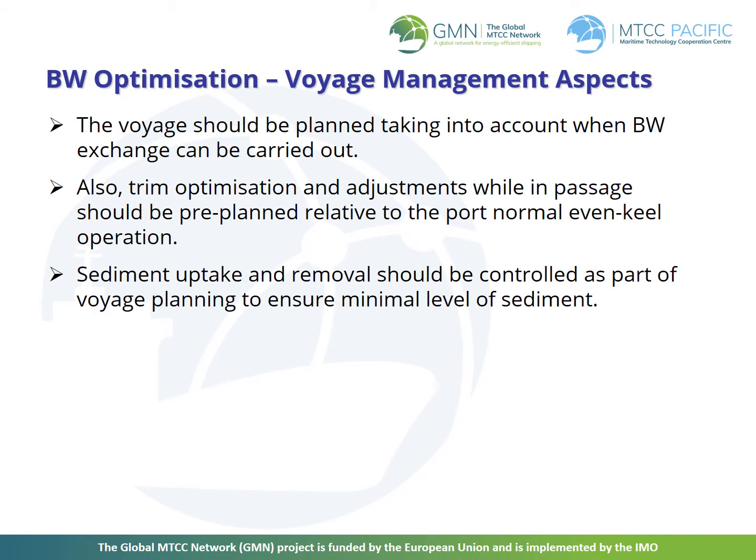The voyage should be planned taking into account when ballast water exchange can be carried out. Additionally, trim optimization and adjustments while in passage should be pre-planned in relation to the port normal even keel operation. Sediment uptake and removal should be controlled as part of voyage planning to ensure a minimum level of safety.